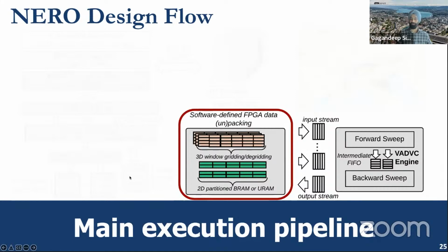And then we create a domain-specific memory hierarchy using the URAM and the BRAM memory. As I mentioned before, the beauty of these FPGAs is that you have so much heterogeneity and you can exploit it and create the memories the way you would like. There are a lot of different ways you can create those, and we use different reshaping techniques to configure the memory space so that we can access these memory elements in parallel for our different processing units. And we use a lot of partitioning of data and various techniques which are known to designers.